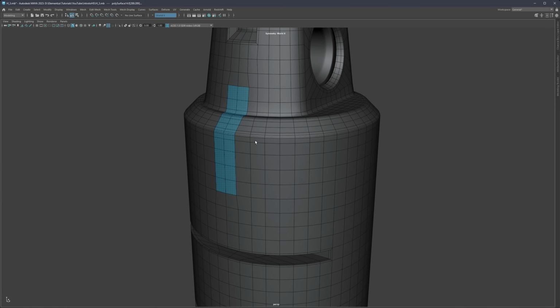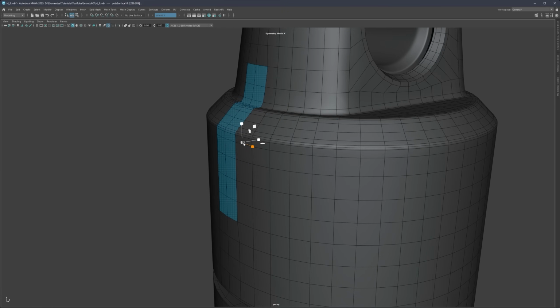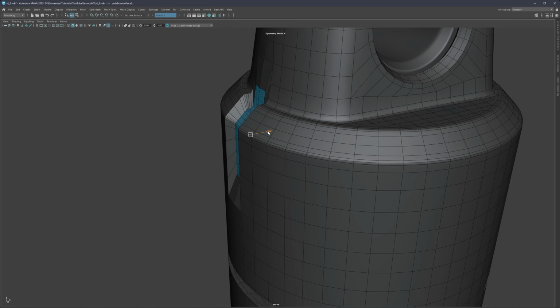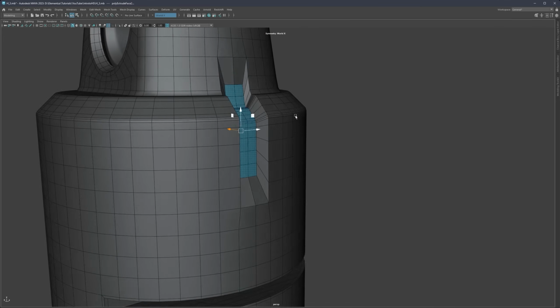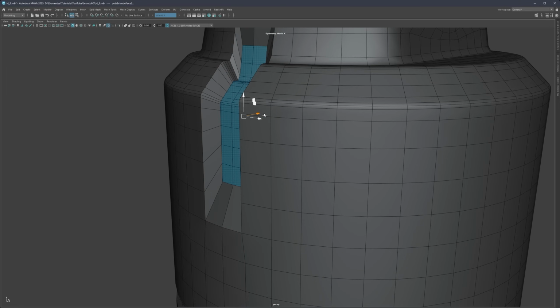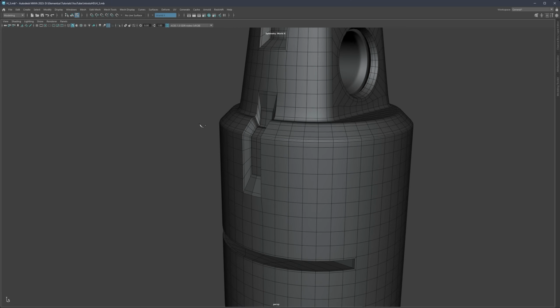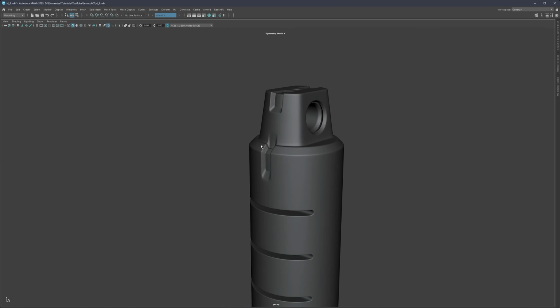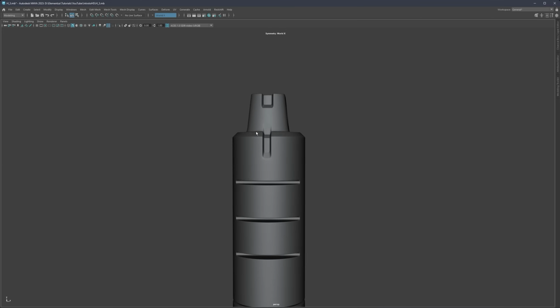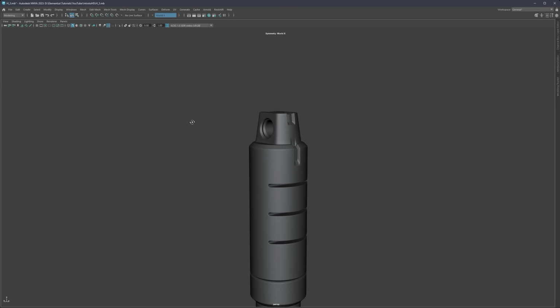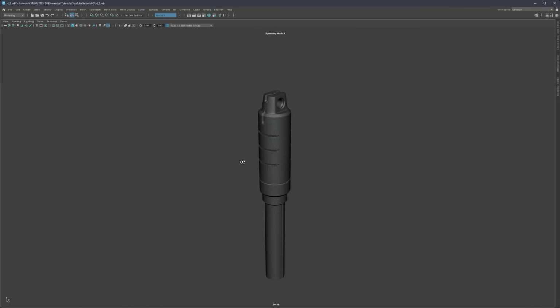All right, and let's go to scale, and then let's now simply, while holding control, I'm going to extrude this on the inside, and also push this slightly on the inside as well. And let's do extrusion, extrude face. And let's go to multi-cut and create one cut here, one cut there, 3 to preview, go to object mode, and there we go. So now we have an interesting looking detail following the same form from the top.